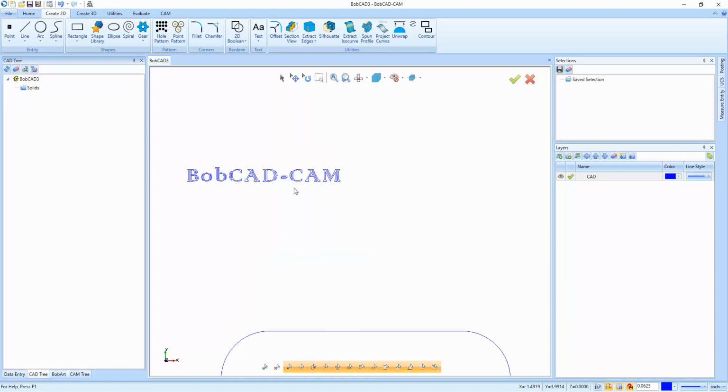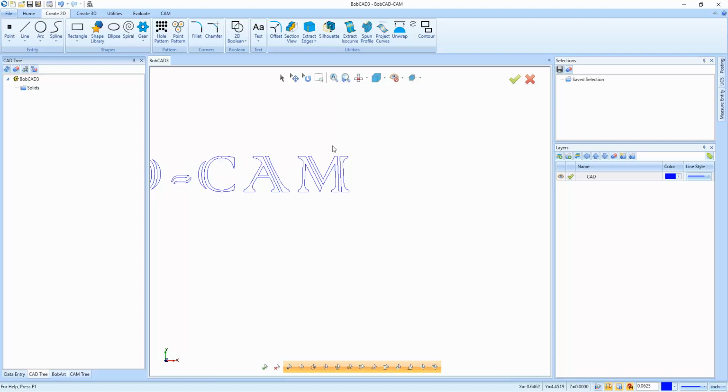All right. The next thing we want to talk about is centerline fonts. So if you notice these fonts here, we have double lines. You have an outside, inside shape, so it has to go around the letter in order to engrave it versus just going down the center. So if you're looking for an efficient part marking notation on a fixture setup or a part number, a centerline font's a good way to go. So let's look at what your options are there.